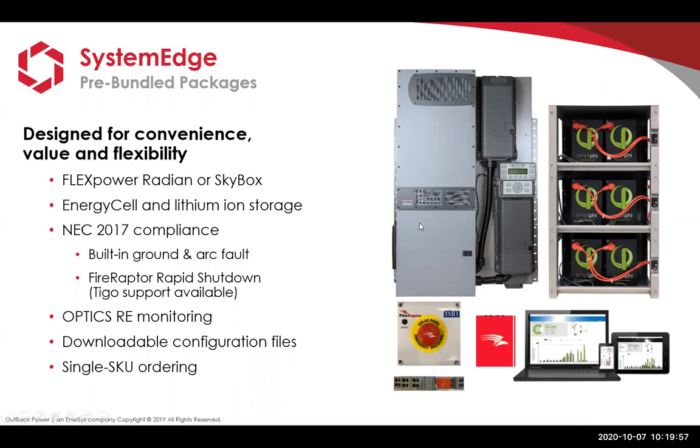And if you've sized it properly to the loads, which is what the tool that I'm going to show you shortly does, you should be all in. So this whole package comes with a single SKU, and the tool will help you find that single SKU that's best for the application. Then you just need to order up some panels, and we also have a string sizing tool as part of that.